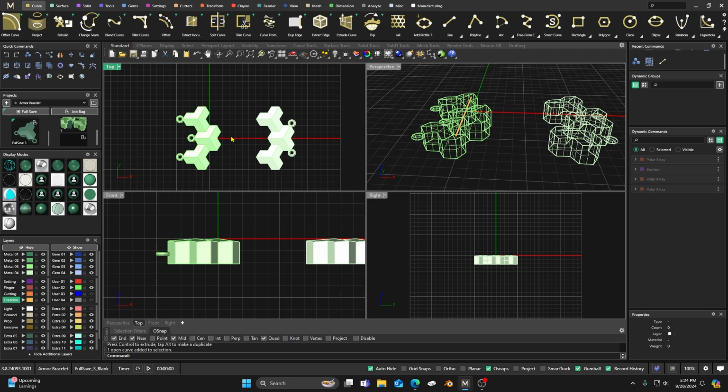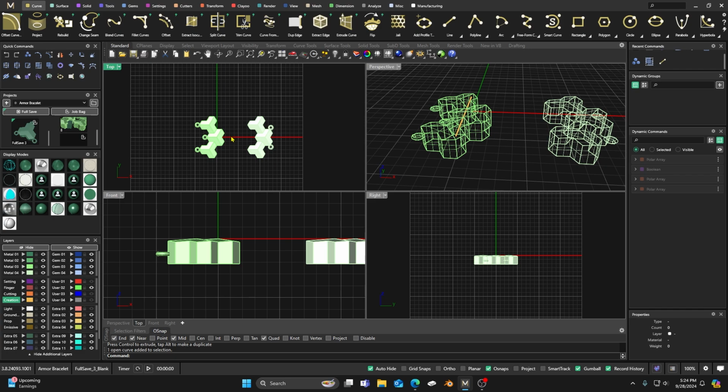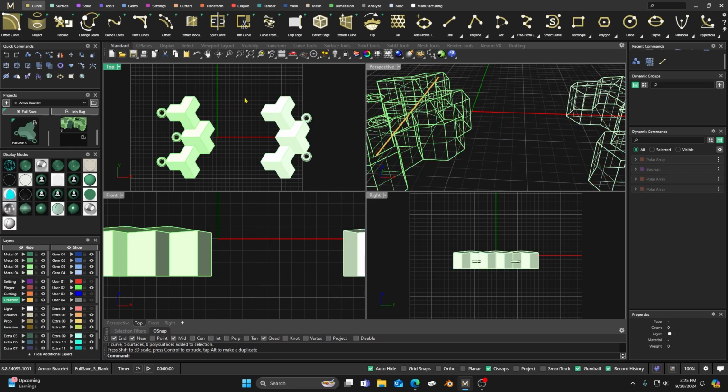Right now it's 10 millimeters. 10 millimeters is probably way too thin. I think if we make it out to more like a watch band thickness, that it might be better. So I'm just going to grab everything, including that little line in there. I'm going to hold down shift, and we're just going to bump them up to around 20 millimeters. Okay, now you can play around with it if you want to make it thinner, but this is pretty much close to a Rolex watch band thickness, so 20 millimeters. So it's not really that wide. If you have a millimeter gauge, go ahead and pull it out and take a look. So it's not real huge, I don't think.